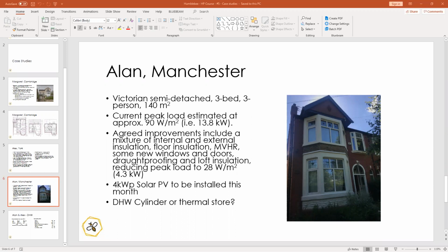But again, there's an argument for using the electricity from the solar to heat the water from whatever temperature it comes out of the heat pump, say 40 degrees, to whatever you want to use it at, because you've only got a low lift. And if you were pushing the heat pump to that, you wouldn't get a brilliant COP out of it.